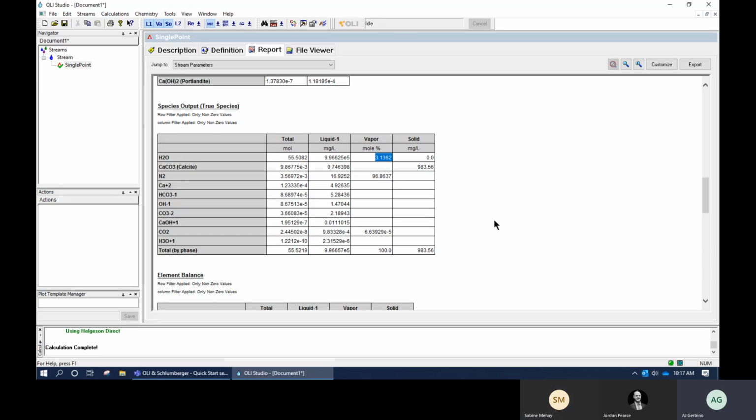This is the water content. And in fact, if you look at that value there, that's about 31 millibars of water, which happens to be the vapor pressure of pure water. So that would be like 100% humidity. So the concepts in the software and what we see in nature are still the same. This is 31 millibar of water. Once I start adding salt to this, you'll see this number go down because the vapor pressure of water starts to decrease as the salinity changes, which is essentially the boiling point rise. So all these things are essentially replicated here.